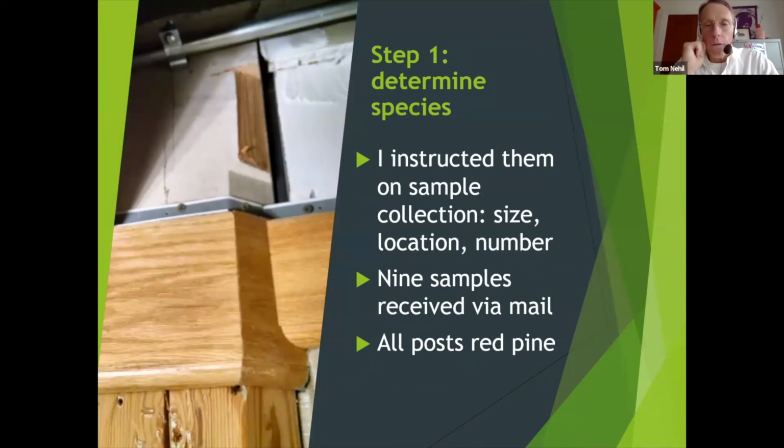Well, step one was then we got to know the species. So I gave the owner guidelines on how to collect samples, and they went through and did that sampling up in areas where it wouldn't do harm and wasn't visible. They sent those to me, so I had a chance to look at those before I'd even been up to visit the site, and I knew then that we had red pine for all of our posts.